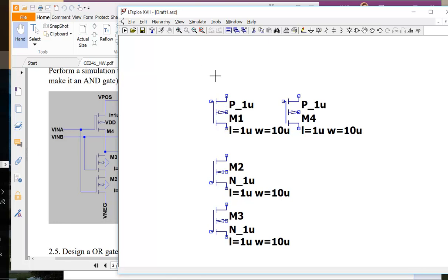So you can press F3 on the keyboard to make the connections. Make sure you are connecting the correct nodes together, but not the wrong ones, like the middle one. And again, you don't have to know why the middle one has to be shorted to the top, because there is a lot of semiconductor physics involved in there.